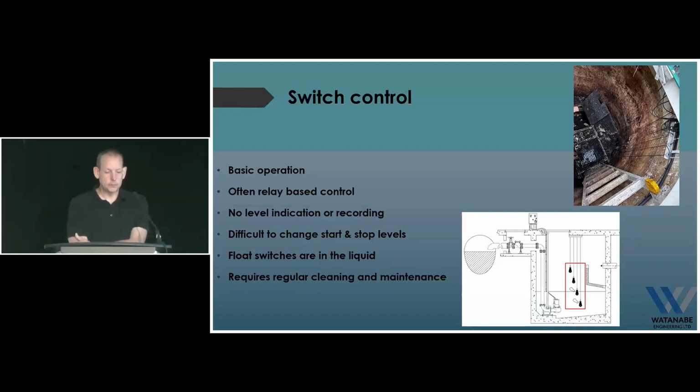But this is a big problem. Does anybody else experience, just show of hands again, anybody else experience problems with float switches ragging up, or in the grease? There we go. So we're seeing that sort of all over the place. So now the big reason that we used to use these is that it was cheap, right? It's cheap technology. It's just a switch, and you put them in, set the level, we're good to go, right? It'll turn on, turn off.